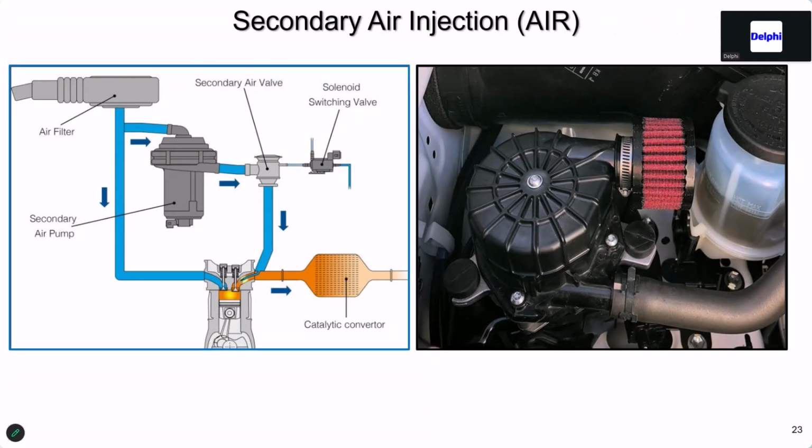Secondary air. This is your one cold criteria. Cold soaks are required. You can do a manual test warm, but for the PCM to do it, it's generally right after startup. The PCM has to issue at least a 10-second command to the system to know that it's been commanded to work, and that's when the test is going to run. Make sure you get one of those.